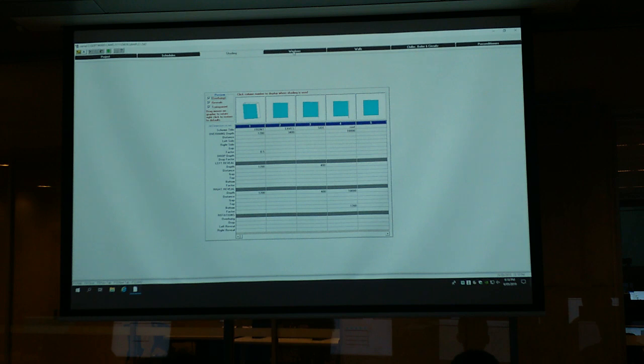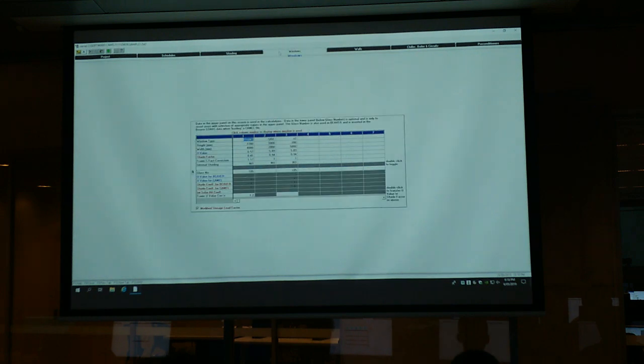All right. Okay. Shading and then windows. You don't need to give all the windows. Just depends on the type. For example, the east wall and the south wall, they have the same size, same materials of the window. You just give one name. Okay, and then later you will locate this name on the east wall and the south wall. Okay, do you understand? It's naming the types of the windows, not each of the windows. Okay.